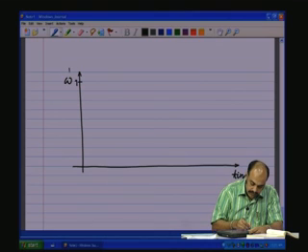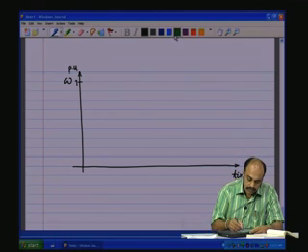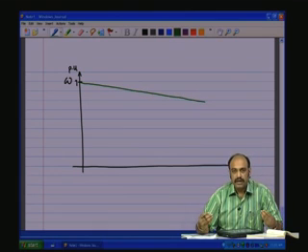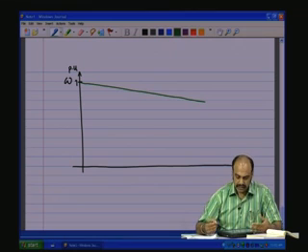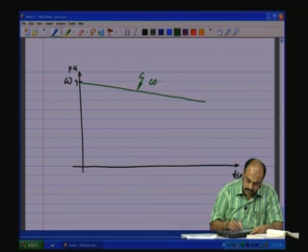This is, let us say, per unit value. It is 1 rated speed. So, when we are coasting, this is going to slow down gradually by its own internal bearing friction, windage loss and things like that. So, this can take quite a pretty long time to come to 0. So, this is coasting.